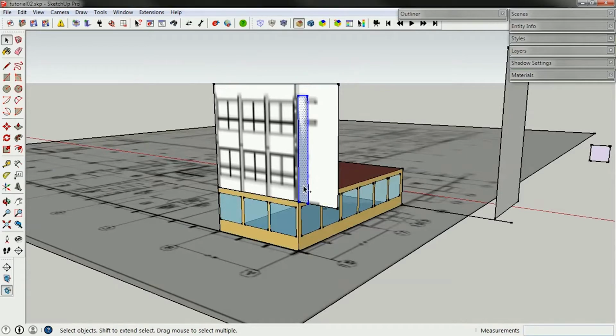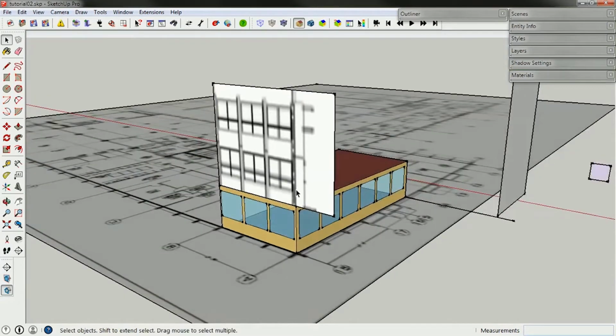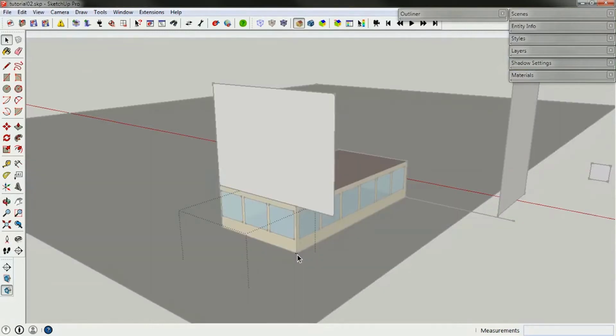So I'm going to cut that, and now I'm going to make a new object called a shading object. You see up here on the top there's this icon, which is a new EnergyPlus shading group. I'm going to click on that and click into my file, and then press Enter to enter that group. And you see I've got everything else grayed out.